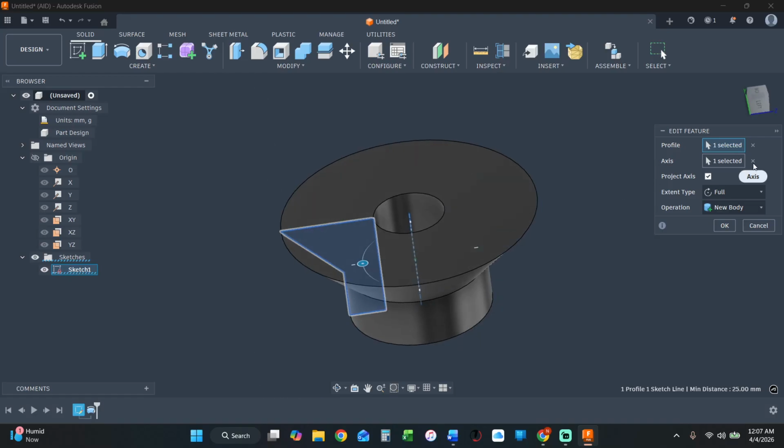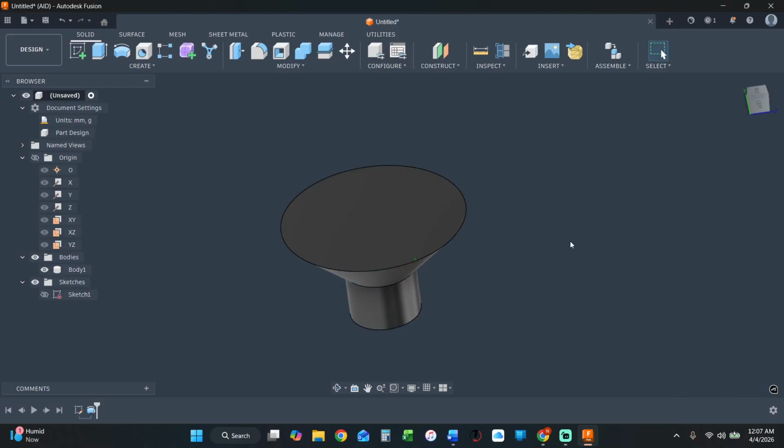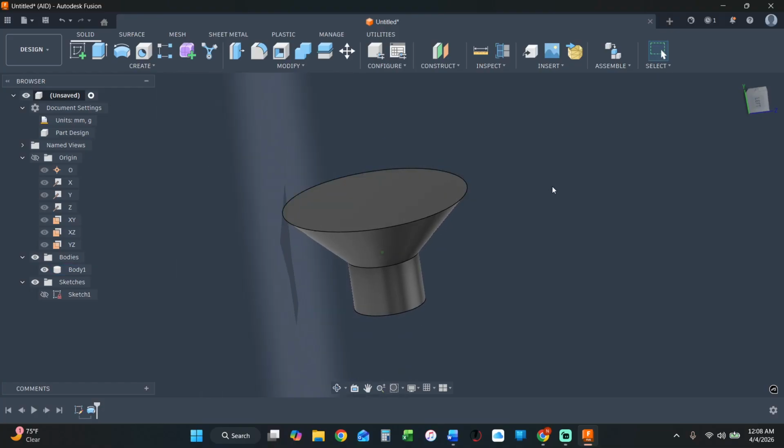So we're going to go ahead and clear the axis. We're not going to delete the new axis that I created and go back to that. Now let's say I wanted a conical feature on the inside that was cut away. So one thing we want to do, especially with round parts, that makes it very easy to draw on. With flat parts, I can come up here, I can create a sketch off a flat plane, but if I wanted to do something in the middle that's conical, I need a plane that's through the center of the part.